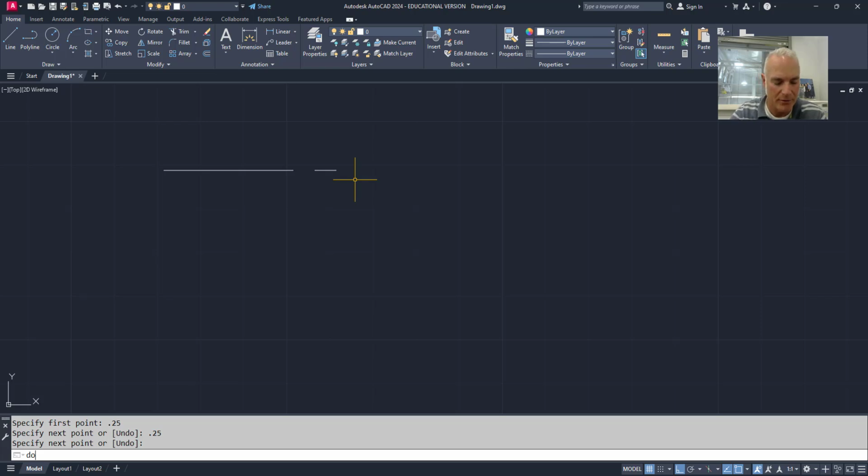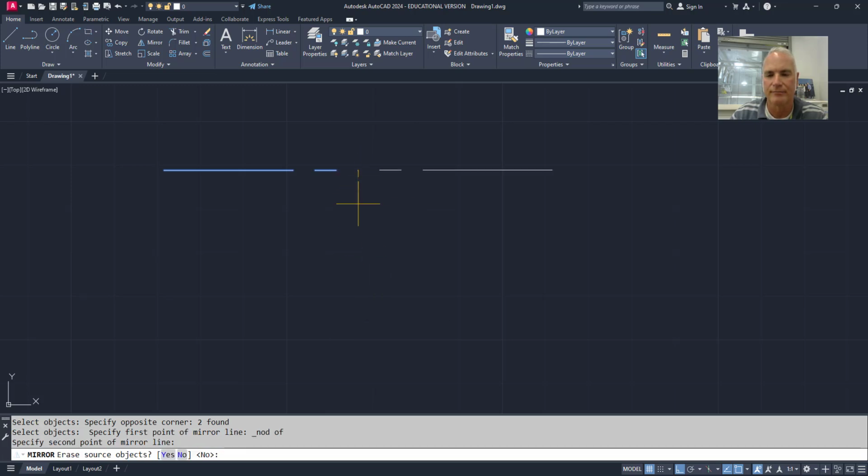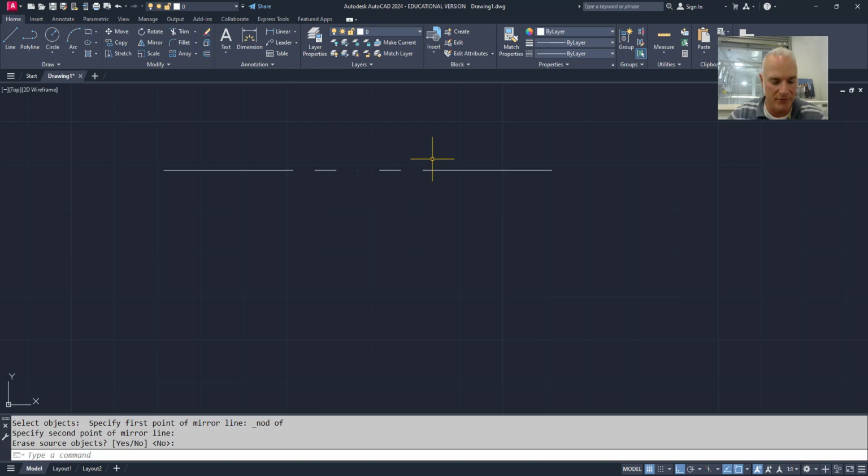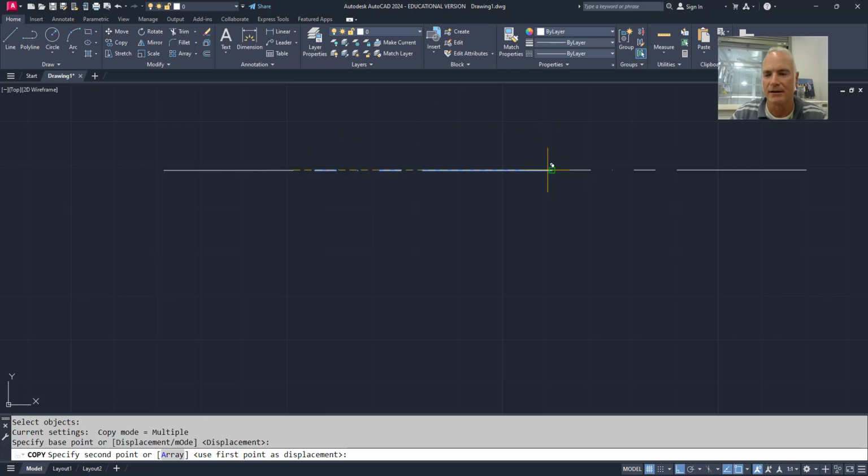And I'm going to put a donut. I'm going to actually draw it as a donut so that you can see it. Well, I'll use a point. If I use a point, I'm going to say, okay, I want a point another 1/4 of an inch over, and then I want to basically mirror this. So I'm going to say, let's mirror this around that node like this. And there we go. So I've got long dash, space, short dash, space, dot, space, short dash, space, and then it starts over again.